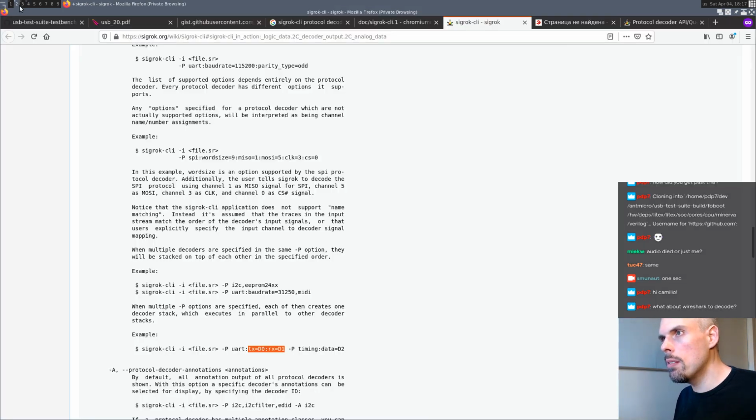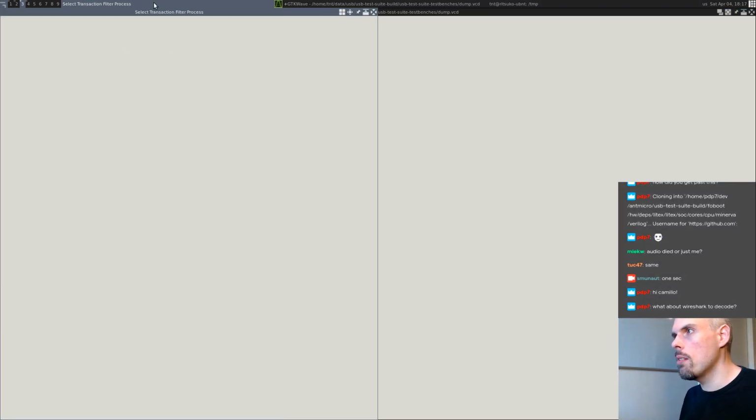I mean, this sigrok integration in GTKWave is really kind of a hack, right? It'd be much better if it was better integrated with like a UI or something, but at least it was quick to write, and it's super convenient. I've debugged SPI, USB, I2C with that.